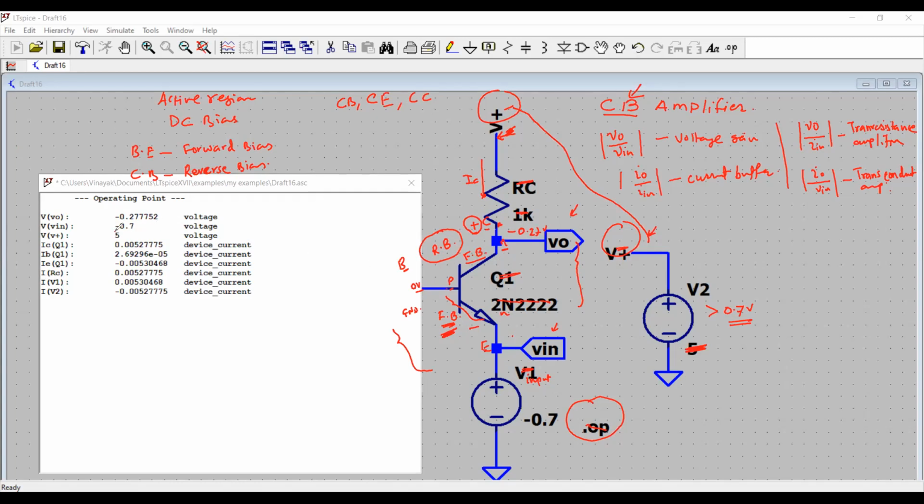How about the voltage at the emitter? It is minus 0.7. So at the N, I have negative as I predicted, and the P, the base, is tied to 0. So this PN junction is forward biased. So both junctions are now getting forward biased, making my transistor saturate. And for amplification, I don't want that. Maybe for using it as a switch, why not? It's possible, but I want a linear amplifier, so we'll do that.